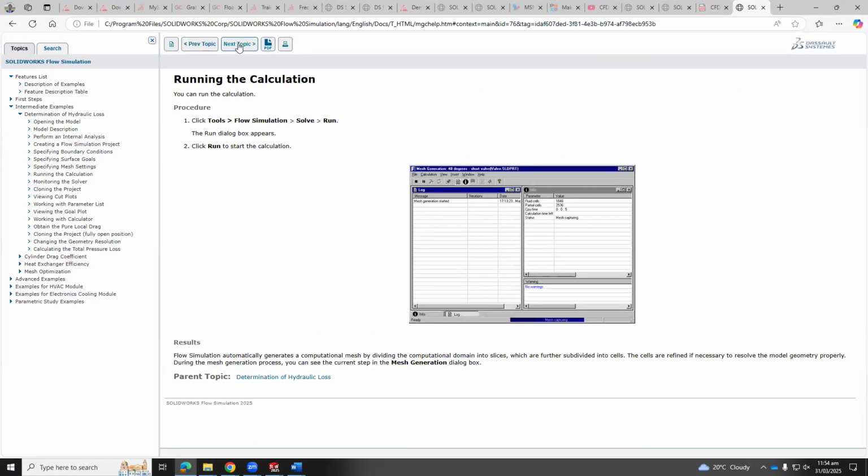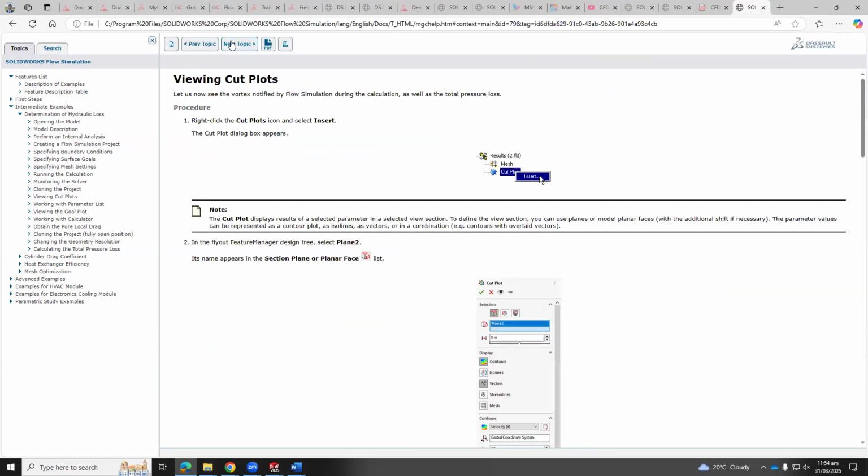Now that is simple. It's not identical to what you'll be doing in the assignment, but when you learn things here, it will help you to understand how you can set up the system, because your boundary conditions will not be at the valve, they will be far away from the valve. We're talking about inlet and outlets. And what you have always, your inlet is inlet velocity. Who decides on your inlet velocity? It's your Reynolds number. So for less than 2000, choose a value.